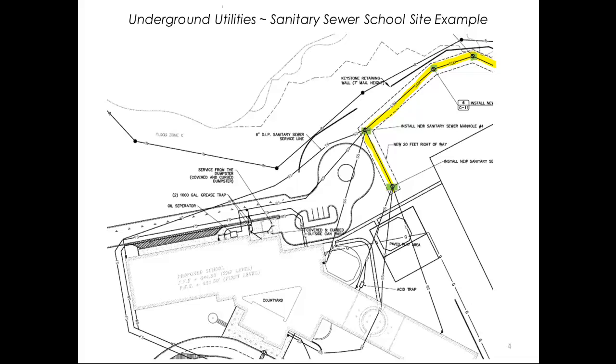Let's look at some of the building lines, and these are labeled SS, and they connect to the last two manholes. From the far right, so we're looking over here, SS, and over here. From the far right, we see two lines that probably service bathrooms, and then to the immediate left is a line with a special acid trap. Okay, see this line coming out here and joining the manhole? This is probably from some type of a laboratory classroom.